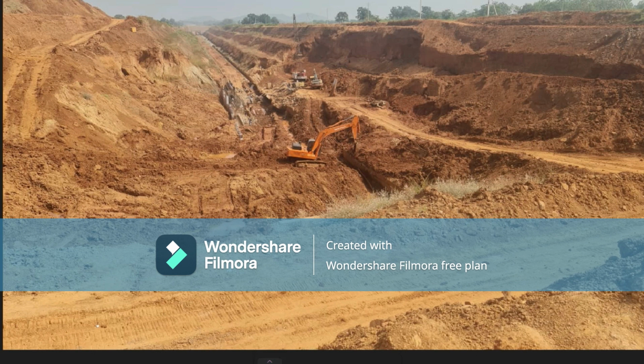After the previous construction, they only provided a retaining wall and a berm, with 3 steps from the ground to the rail track level. But during the rainy season, due to poor water pressure, the slope was not stable and failed onto the railway track, sliding the slope. So after that, we have to reconstruct it to prevent the slope failure and to stabilize the slope. They reconstructed here.